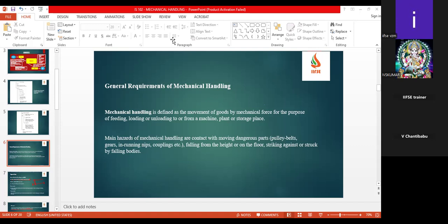With that also, I have seen some facilities doing the load test. Instead of getting the big size blocks, they will create a provision anchor on the floor itself. They will tie up with that anchor and they start pulling it out. That is also one practice.